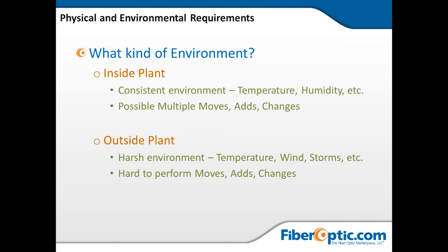Make sure that if you're going to be adding active equipment, your environmental controls are sufficient, not just for today, but maybe I have twice as much equipment in there 2 years from now. Is the existing AC going to keep that cool enough when you double the heat production? So you have to look at the future. You always have to look at the future.